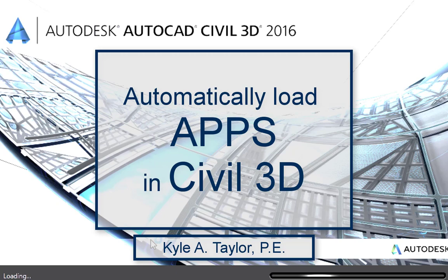I'd also say you have the option of calling the file name acaddoc.lsp, but AutoCAD treats this file slightly differently, but I've used both over time and haven't found any difference. Also add that method number two may be a little bit more flexible because there isn't any name requirement for method number two. You can call it whatever you want. You can add as many individual .lsps as you want. So using method number one, all of them have to be combined in a single .lsp file.